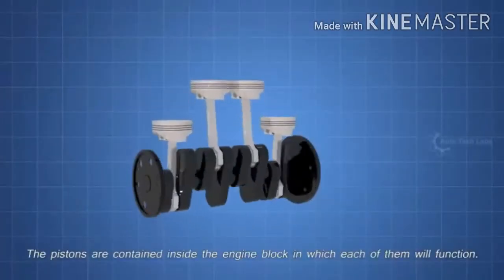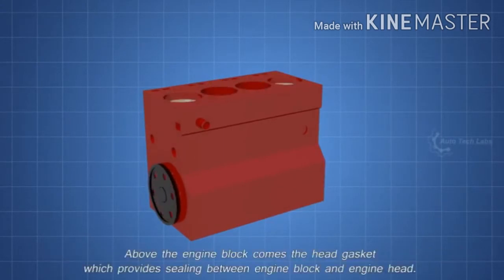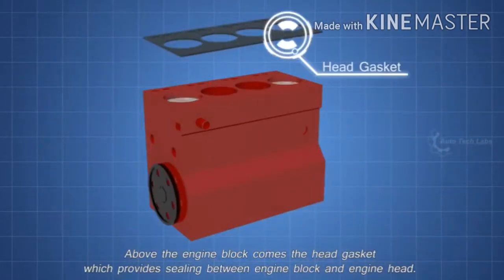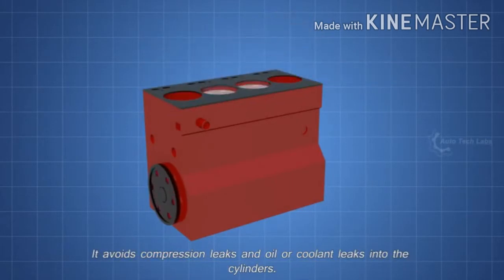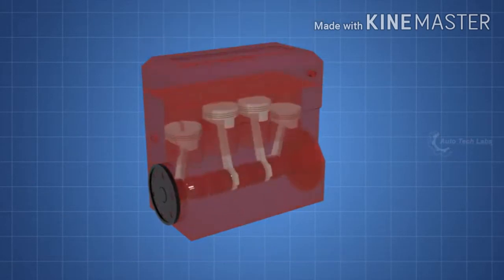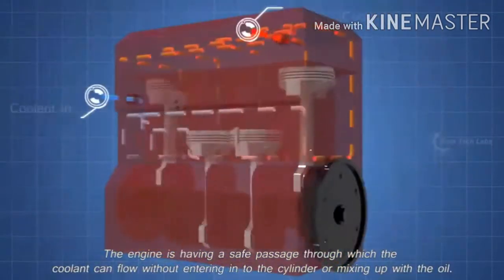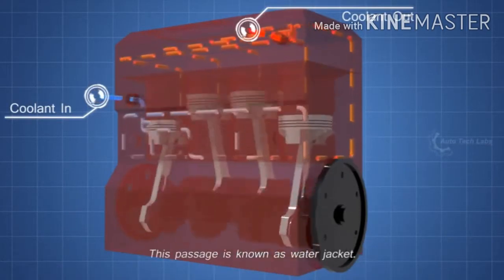Now, let's see how these parts work together. The pistons are contained inside the engine block, in which each of them will function. Above the engine block comes the head gasket, which provides sealing between the engine block and engine head. It avoids compression leaks and oil or coolant leaks into the cylinders. Above that comes the engine head. The engine has a safe passage through which the coolant can flow without entering the cylinder or mixing up with the oil. This passage is known as the water jacket.